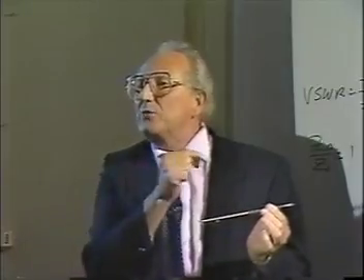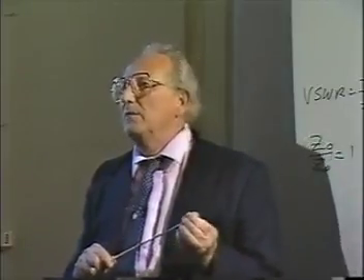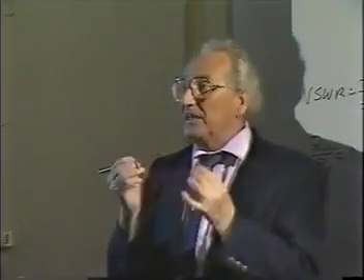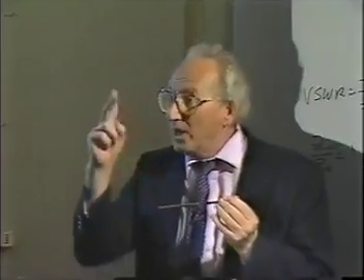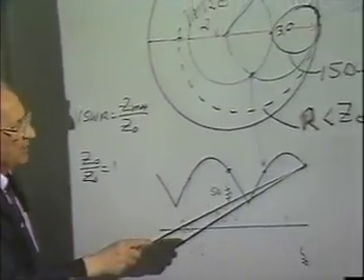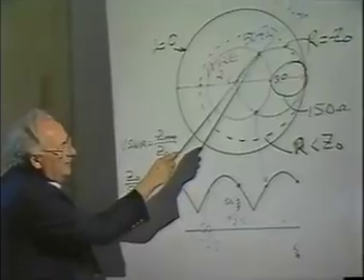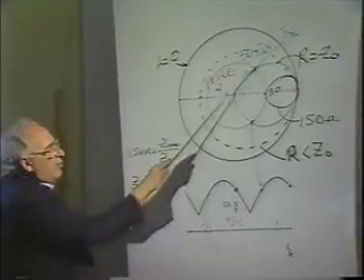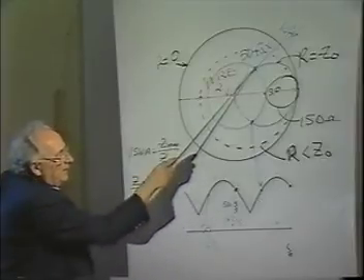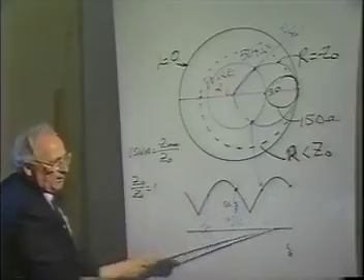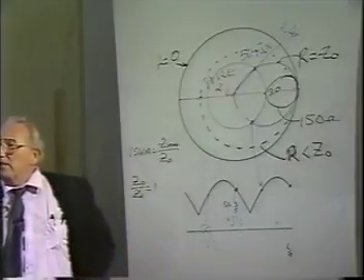But I'm going to explain this right now in terms of impedance so you know what we talk about when we talk about impedance matching. But think of this in terms of a two-wire line that I can actually physically open and put something in series with the line. Two-wire line. Notice this. If this point here happened to be this point here, then at that point where the load is, if I can open up, take the load off, and put in a value of capacitive reactance in series with that load right at that point to cancel the inductive reactance, what do I have left?